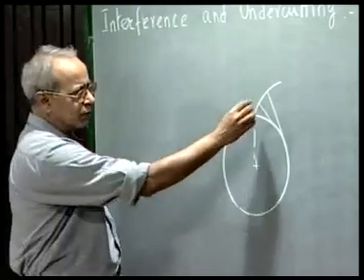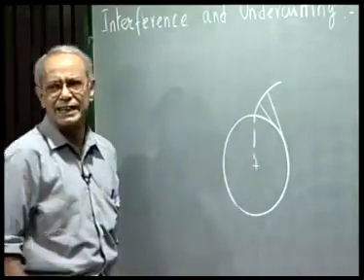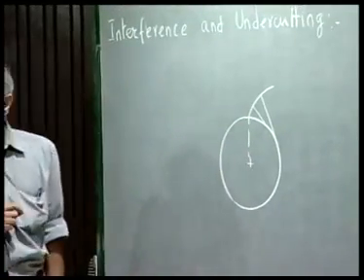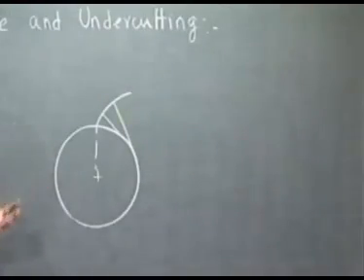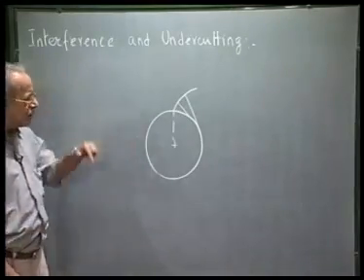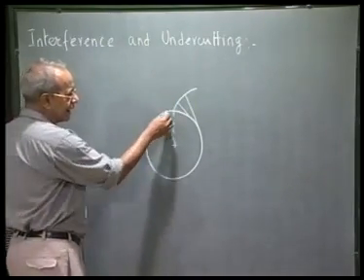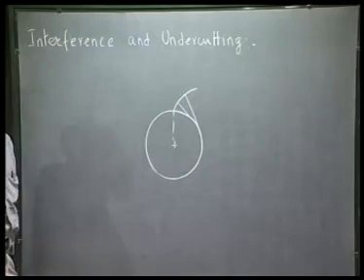So the involute profile exists only outside the base circle, does not exist inside the base circle. Suppose we use very few number of teeth on a gear and the teeth size is very big, then it may so happen that the addendum circle of the mating gear gets into the base circle of the other gear.